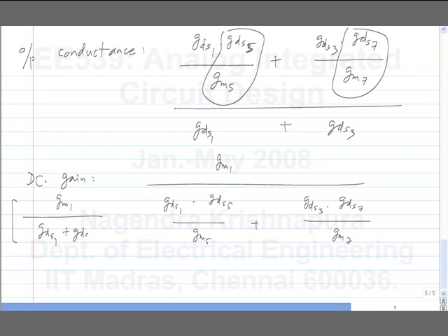So we have gone from some number which is of the order of GM by GDS of a single transistor, to something that's of the order of GM by GDS squared. So the DC gain you get from this is, in order of magnitude, similar to if you had two stages in cascade. Is this clear? Is the analysis of DC gain clear?